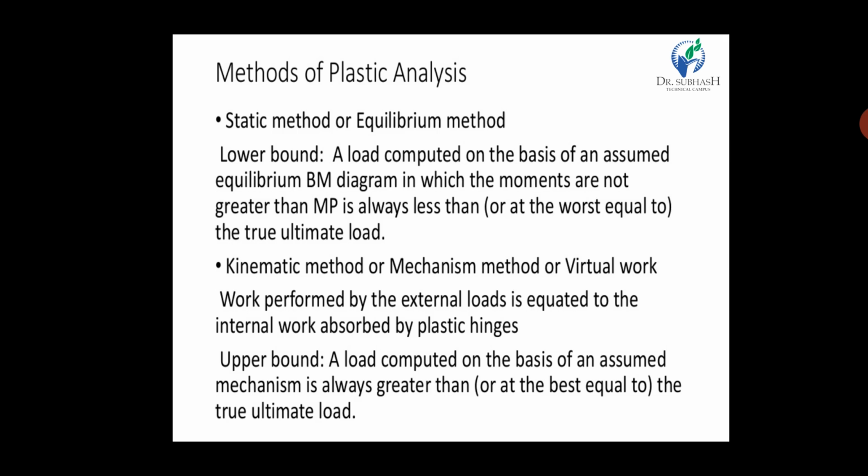Now the methods of plastic analysis. The first one is the static method, or equilibrium method. The lower bound: a load computed on the basis of an assumed equilibrium bending moment diagram in which moments are not greater than Mp is always less than or at most equal to the true ultimate load, and this should be satisfied. Now the second is the kinematic method, or mechanism method, or you can say virtual work.